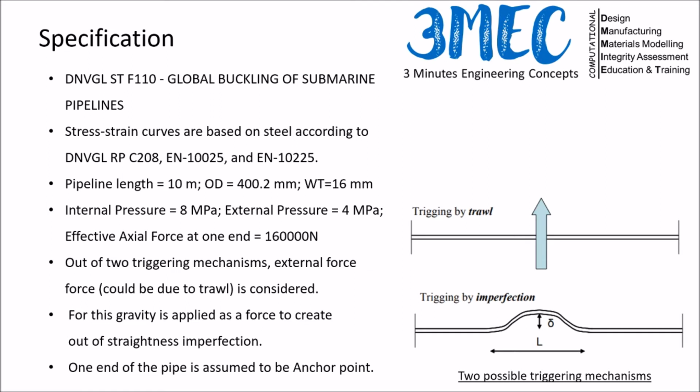They all ask you to define the plastic part of the stress-strain curve if you are using nonlinear finite element methods. I'm assuming my pipeline, again, as an idealized case. All similarities will be coincidental. My pipeline length is 10 meters. Generally, pipeline lengths are in kilometers, thousands of kilometers in some cases, so this is a very short length to do a buckling analysis, in my opinion.